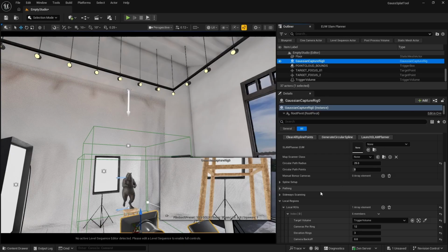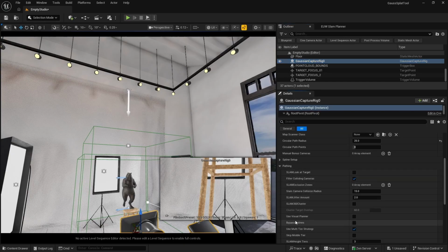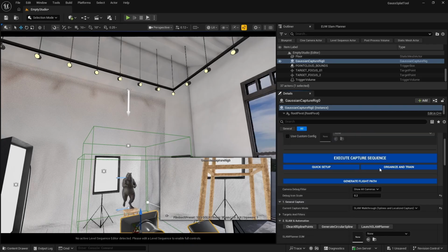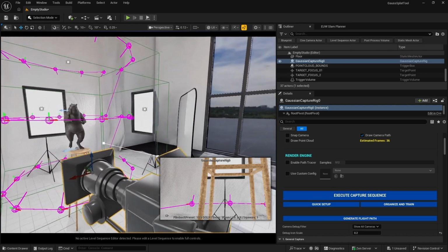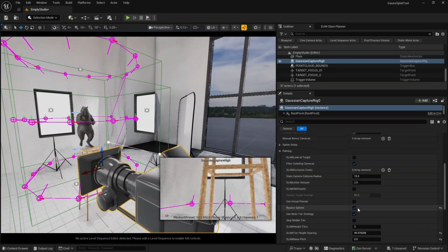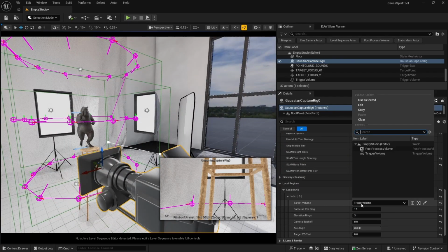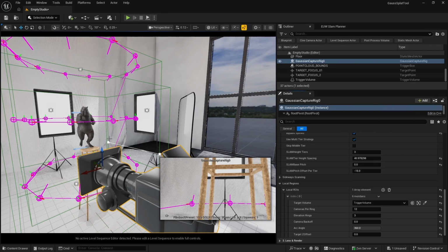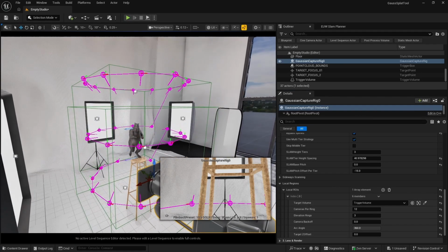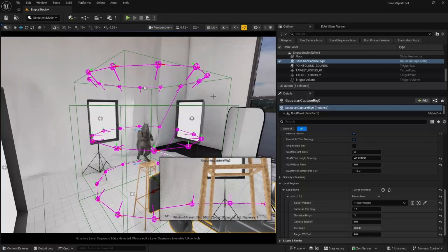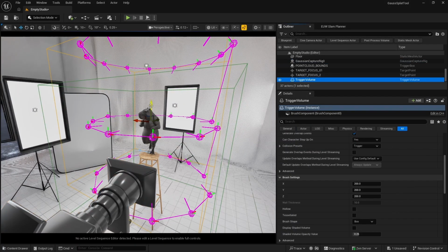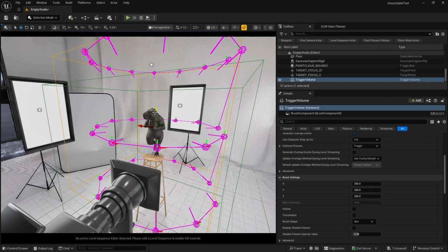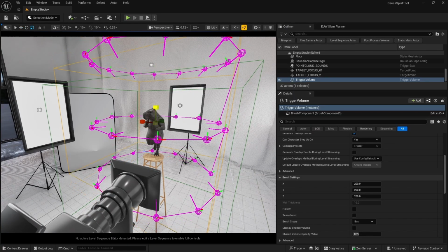And then in this option, go to the pathing. There's an option to bypass the splines. I'm just gonna turn that on, so I don't generate any camera nodes using the spline. And then when I draw my visualizers here, you can see the trigger volume we made defines the bounds for the curves and for the path generation. If I scale the trigger volume, the paths scale accordingly.